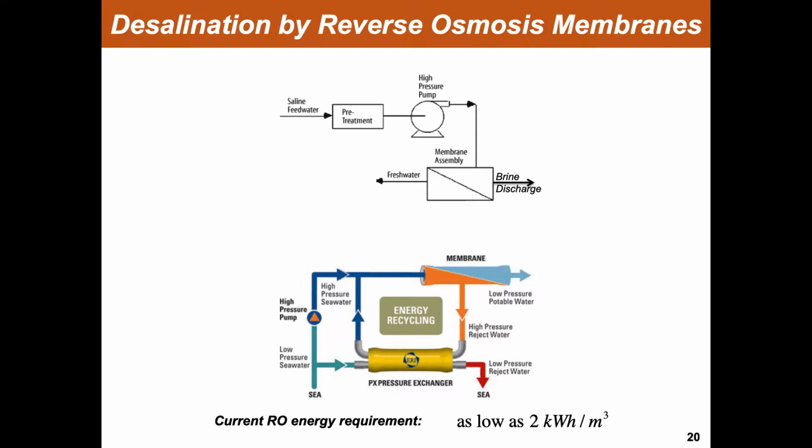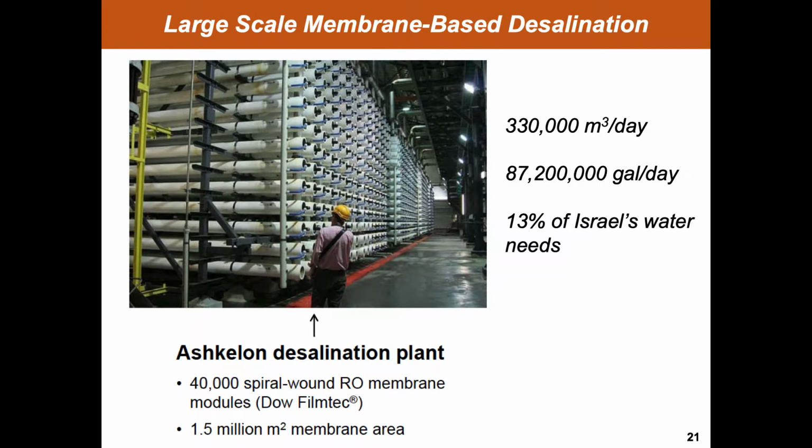And there have now been developed mechanical systems called pressure exchangers that allow one to recover a lot of this energy that would be in the brine discharge that's at high pressure, and exchange that with feed water, and this contributes to high energy efficiency in these devices.